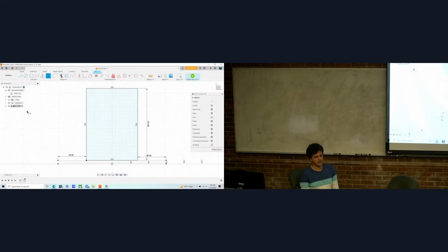Okay. Now, if I wanted to know right now if this sketch is fully constrained, how can I find that out? So you go to the timeline and then click on sketch. And you should go down to sketches down the left. We'll open the component, we'll open sketches, and there is a lock there. So we do have everything fully constrained.